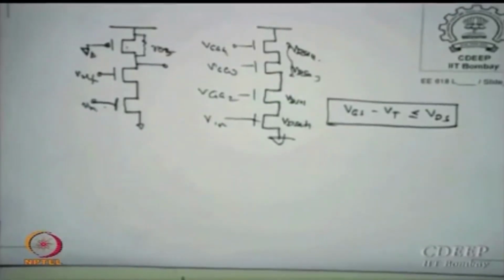So I will show you an op amp which is a telescopic op amp, which has its own advantages at some cost. So we like to see that putting things in series may not be as advantageous as it looks. If you have a 3 volt supply, fantastic, no problems. At 1.2 there is an issue, and why I keep saying there is an issue is because now the power supply for the digital part is 1 volt, and I am forced to work with them independently.